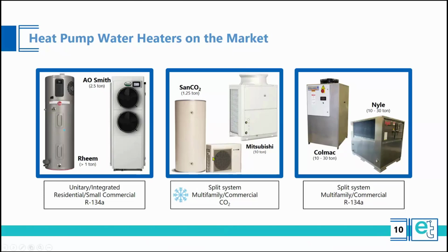The CO2 also has specific usage which it operates well in. So it operates very well in the cold climate, but also requires cold water to operate efficiently, cold intake water. It doesn't operate as well when the water coming in is warm. And so those work well, as I said at the beginning, in a single pass, in a single lift, whereas the ones with the other refrigerants might work better with warmer water and multiple passes.